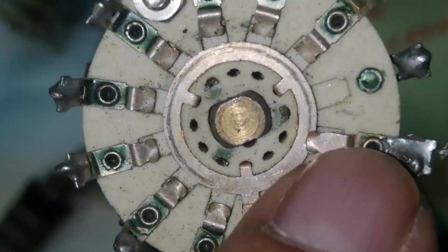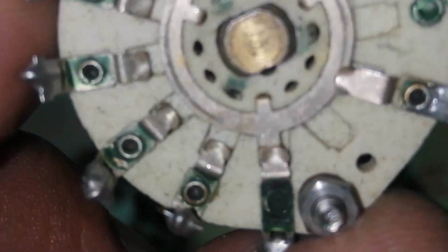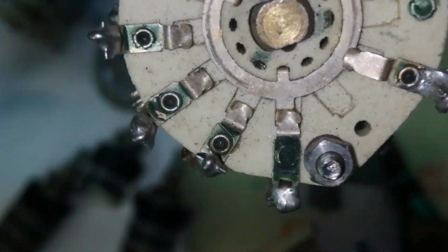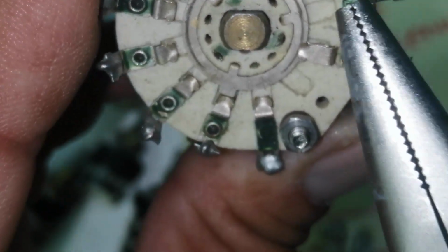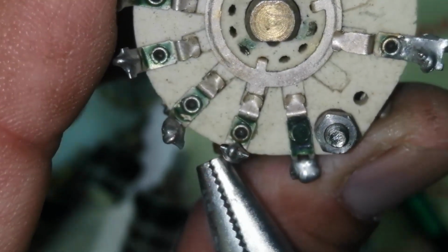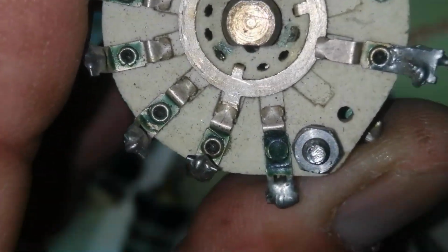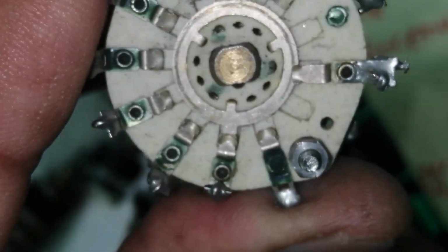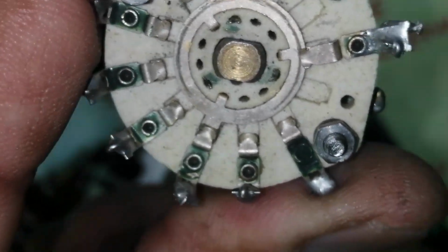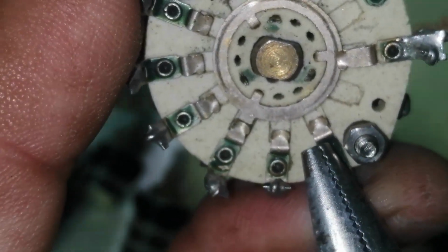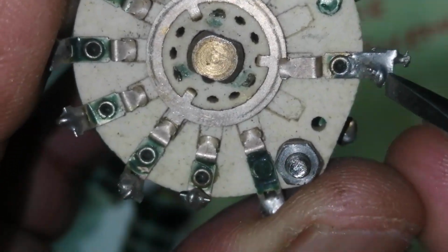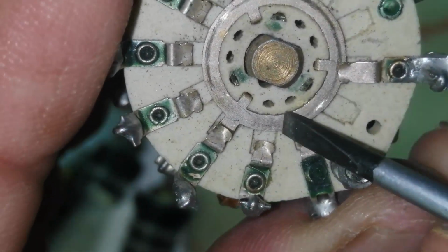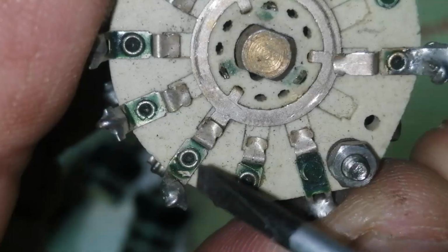Now one line is connected here, and this time the common line and number 1 contact have connection. Now number 1 line, common line, and number 2 line are connected. Number 1 is disconnected, and if I move more, common line, number 1 is off, number 2 is off, number 3 is on. Now we can see the current will flow from this end to this plate and go out from here. Because this is disconnected, it has no connection now. Now we will return back here.